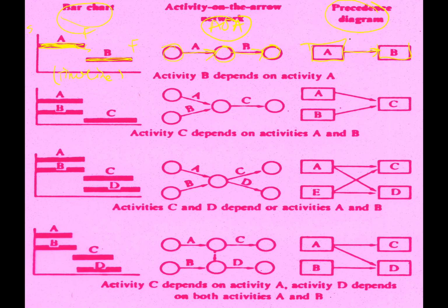No, finish to start. Relationship is FS. Okay, second, you notice that A and B are basically concurrent activities running at the same time, starting at the same time, and then only C will follow. Okay, C will follow. You see, we can draw something like this.